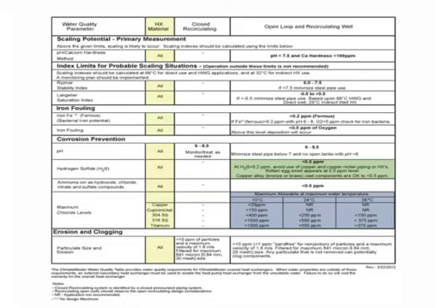All right, so let's spend a few moments here. This again is in the ClimateMaster, but is very similar in other manufacturers' literature. This is the water quality parameters. You're going to see some columns here. I've highlighted a couple. The off orangish or off white is HX material, in other words, heat exchange material, because you do have some options and there are sometimes you want to start making some changes. You can see as you start to go through some of the acceptable limits for that water condition. You'll see to the left the description, and over to the right you're going to see what range is acceptable and/or what you may want to consider doing.